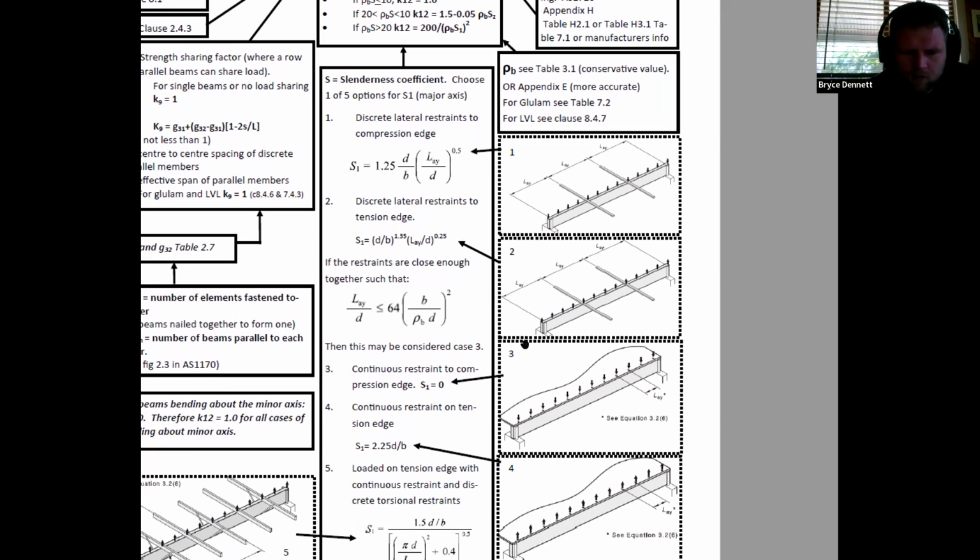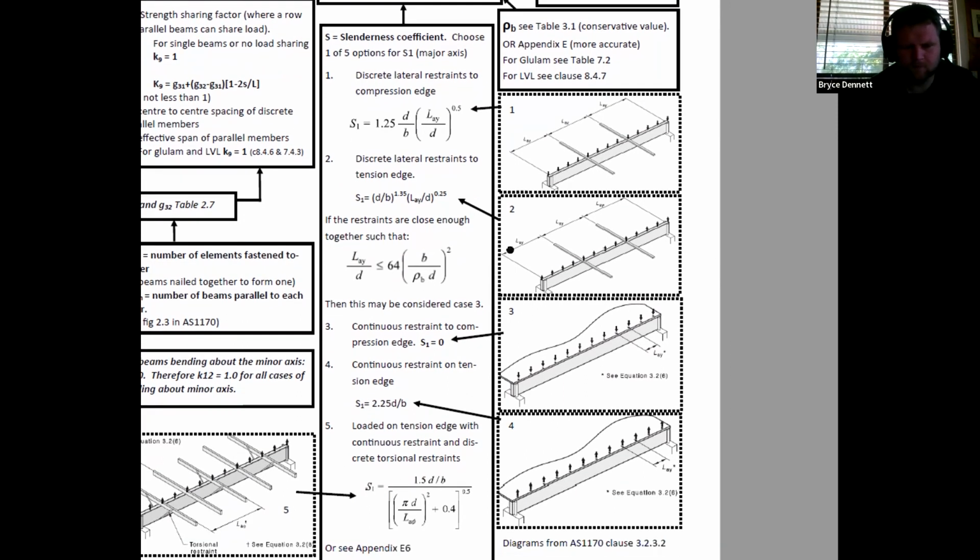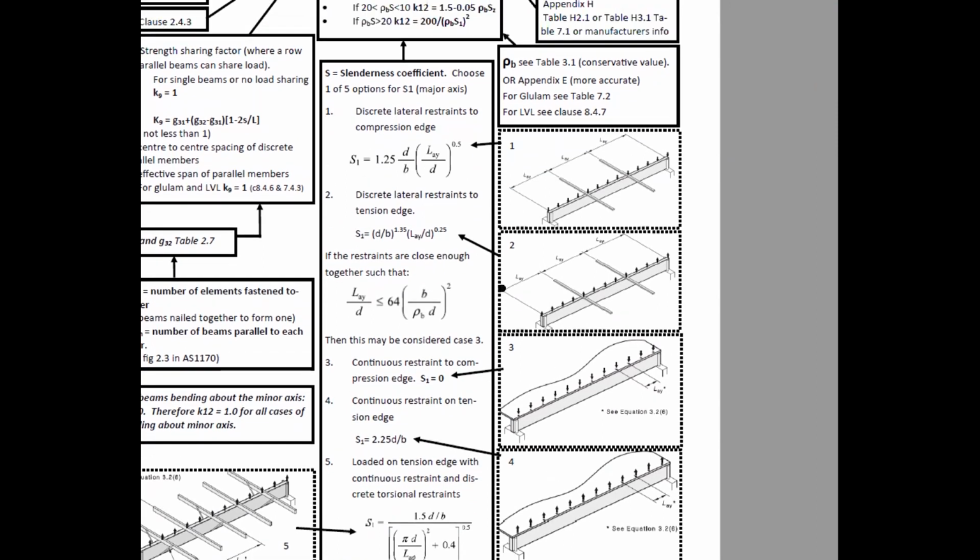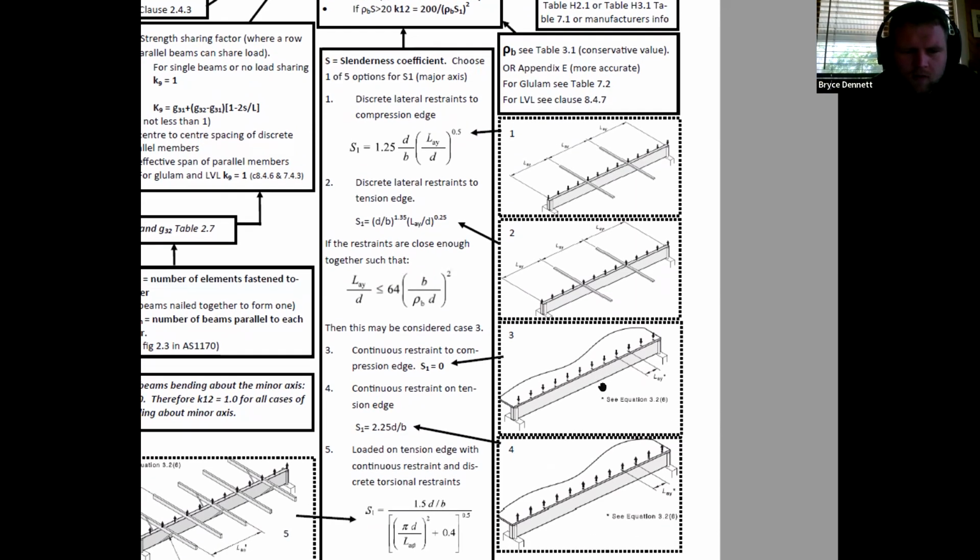So which formula should we have gone with? Because it seems to be restrained with the floorboard going on top of a beam. I went with 1. There wouldn't be a wind resistance. You should have gone with either. Okay, and the load is down, right? If the load is down, then you're talking about number 1 or number 3. If we went with 1, didn't we, Ian? Yeah, but we tried using that LAY on D to try and verify it first. That's right, probably where we went wrong. Okay, so it's either 1 or 3.